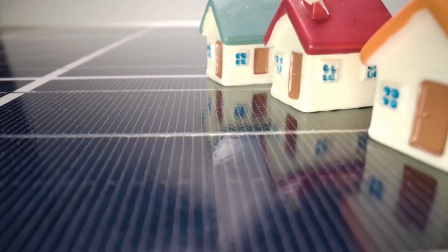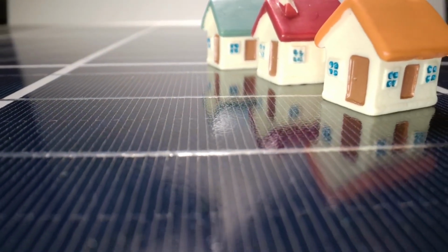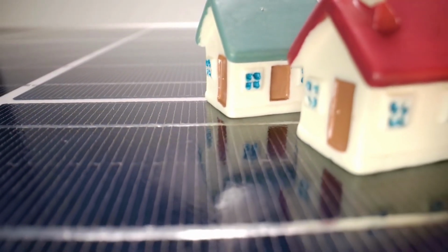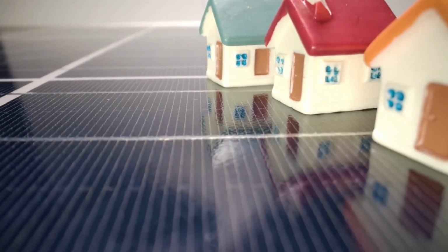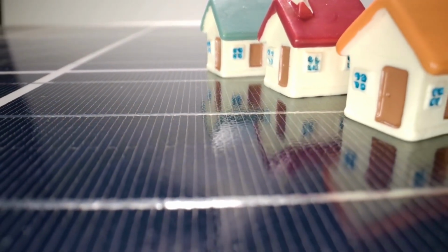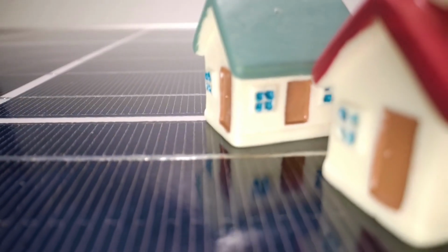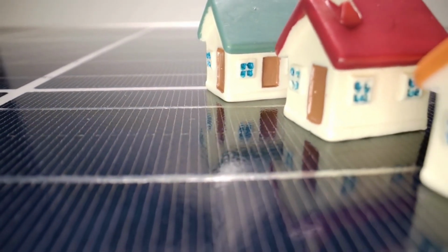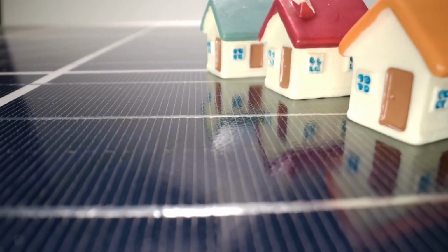HVAC systems operate at peak loads for less than 1% of annual hours but at partial loads for thousands of hours. Designing for intermediate conditions rather than peak conditions may improve overall system performance. Building America has developed guidance documents for load calculations, equipment sizing, and air distribution. Room-by-room CFM requirements often differ significantly between heating and cooling modes, requiring careful balancing.